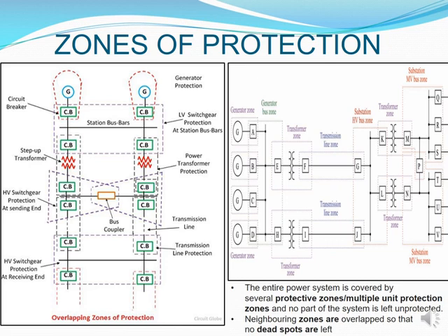Okay, then your P that you are seeing there is a similar thing as your bus coupler that you had seen before on our left hand side, but because it's on the MV side, we usually call it a bus section, which really all that it does is to put the 2 buses together. So in case the one bus bar cannot fit where you've got your Q, R, and S, then you would be able to take that transformer and feed it into the T, U and V bus bar with the second transformer that was in there.